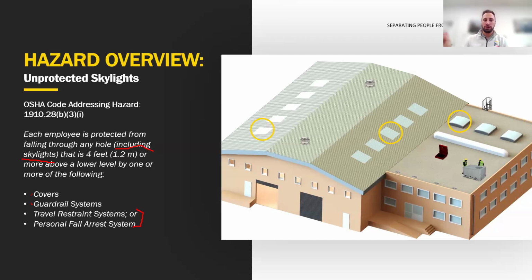So these may be new terms for you. I don't want to assume that everybody's gone through their OSHA competent person class, but if you were to go through your OSHA competent person fall protection course, what you would learn about are the ABCs of fall protection. So here's a non-accredited 30-second OSHA competent person class. ABCs of fall protection. A stands for your anchor. So it's what you're tying off to. It's an anchor point or horizontal lifeline on the roof. B stands for your body harness. So the thing that you're wearing that you're going to connect to the anchor. And C is your connector, the lanyard that connects your body to the anchor, right?